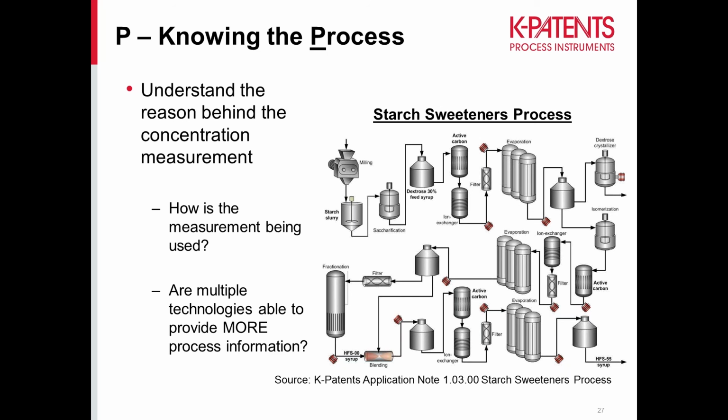And then also, of course, what makes it even more common is the outlet of the evaporator. What's coming out of the evaporator is that finished product. Now you know, has that worked correctly, and do you have that liquid concentration in that targeted range? So if you're looking for okay accuracies, mass flow is okay for that particular application. But if you're really looking for fine-tuning that information coming from that evaporator or going into the evaporator or coming out, you can use a refractometer.